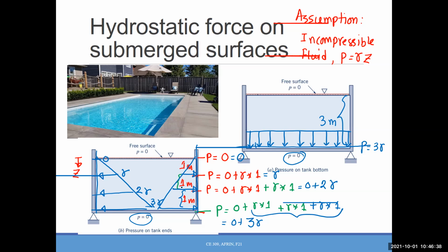Now, one tricky question I can ask you for your test or something. Do you think this pressure distribution will be always triangular, like for the vertical plate? No. When can it be different? Yes. So there can be 2 types of answer. The first answer can be if we don't use the straight plate, if it's curved surface, obviously the pressure variation will be different. We will discuss that. But just for the vertical plate, the pressure can be different if you use compressible gas.